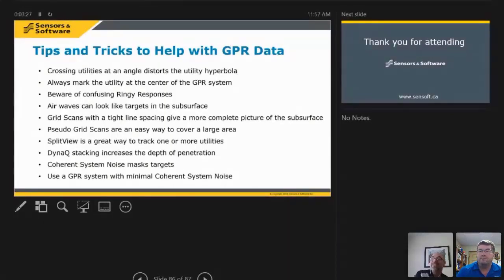Chemicals, the objects in the water, which drive up the conductivity of the water, which makes it saltier, is what absorbs GPR signal. So I've seen a lot of cases where water has actually improved the image of the data. And people probably won't believe that, but it's true. I've seen cases where that occurs.